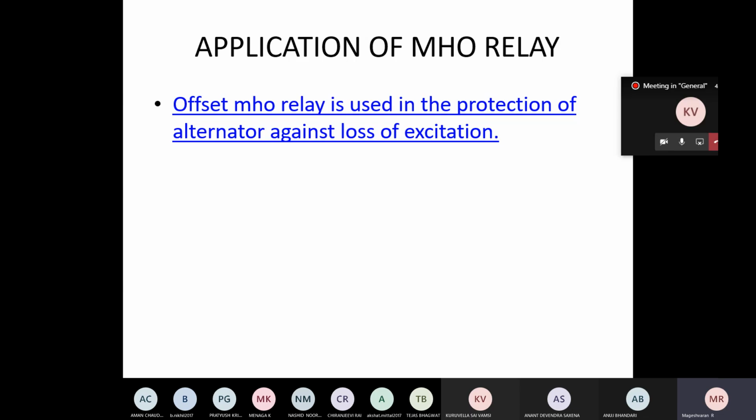But when it is acting as an induction generator, it is going to run at high speed. It is going to take reactive power for the production of magnetic energy, so it depends on the grid. Because it is connected to the grid, many sources will be there. It may be one of the alternators in that grid, so the other alternators may support, if it is feasible.